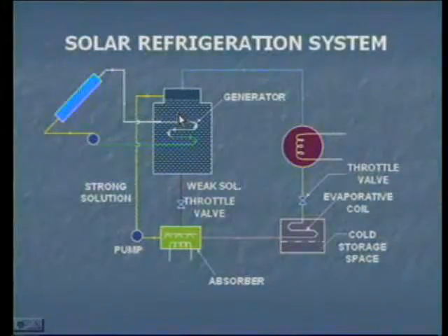So there is no direct contact between the refrigerant fluid and the water. By absorbing the heat from the hot water flowing through the pipe, the refrigerant phase changes to vapor. That vapor moves within the refrigeration circuit. In this manner, solar energy is utilized to convert the phase of the refrigerant in the generator of a vapor absorption refrigeration system.